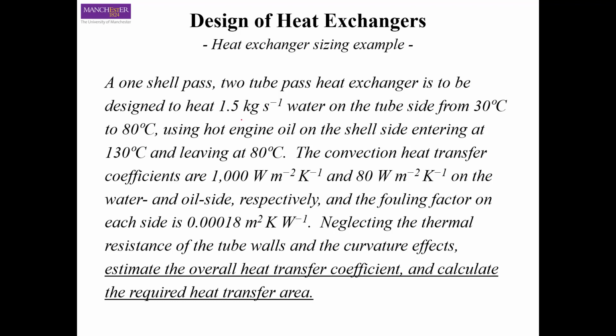So you have the cold fluid, that is water, entering at a temperature of 30 degrees centigrade and coming out at a temperature of 80 degrees centigrade. Then you have the hot fluid, that is the hot oil, and it is in the shell. And the hot fluid enters the shell at 130 degrees centigrade and leaves the shell at 80 degrees centigrade.